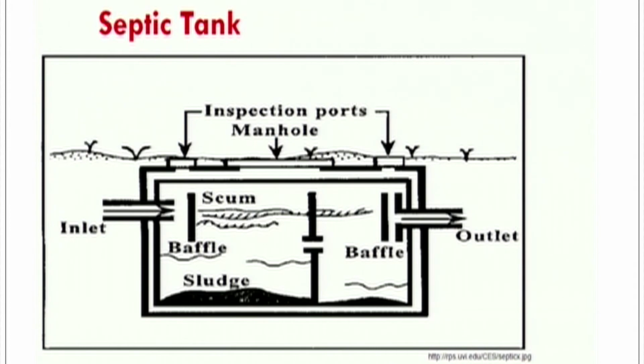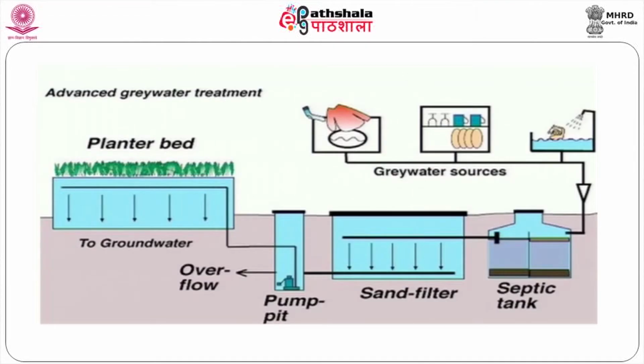The gas can be directly released into the atmosphere by providing ventilation ports. Ventilation ports are provided here to relieve gases generated during anaerobic decay. Once in a year or once in 2 years, we have to remove the digested solids accumulated within the reactor. This is a trench facility that we have already discussed.